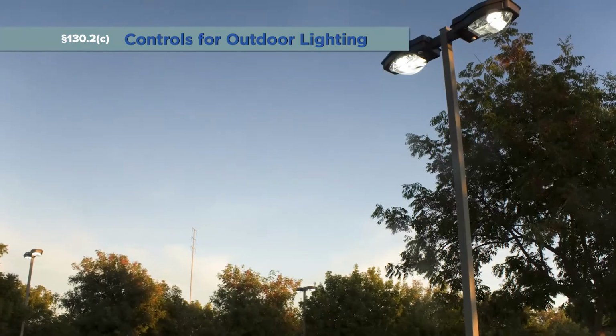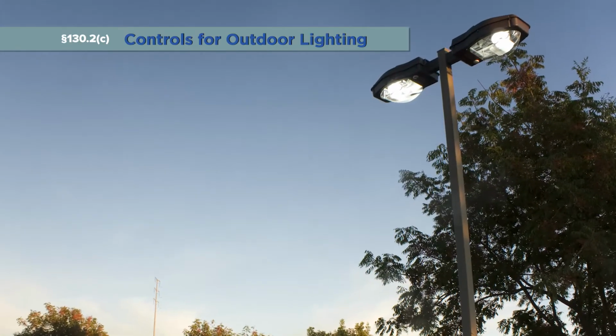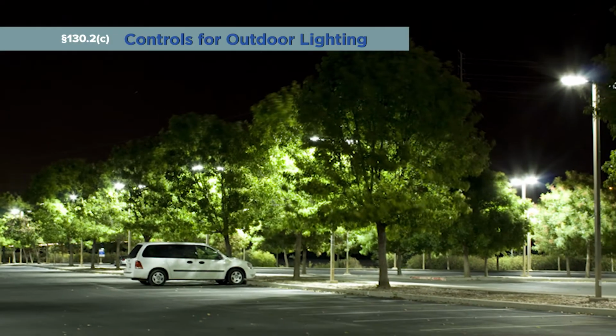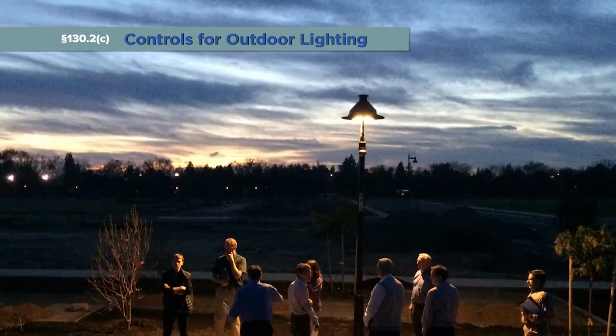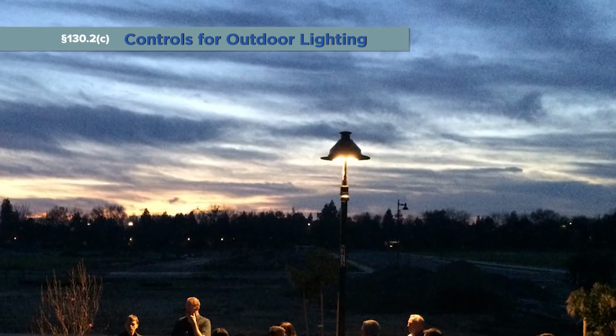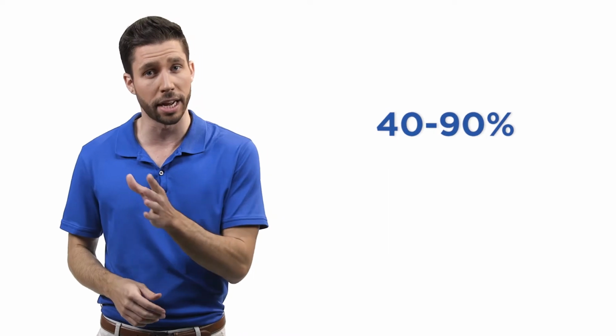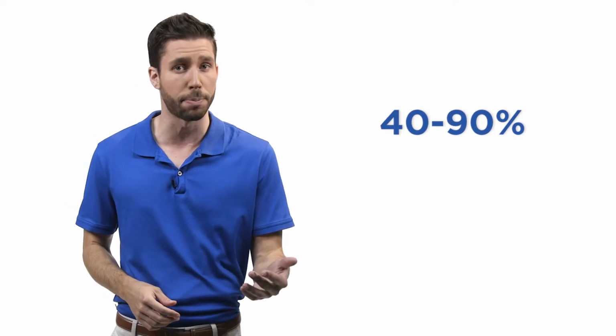Motion sensors in outdoor areas work well as a partial off device, meaning they turn off only a portion of the lights at night. This saves energy and maintains a low light level for safety and wayfinding. These controls must be capable of automatically reducing the lighting power of each luminaire by at least 40%, but not exceeding 90%, or provide continuous dimming through a range that includes 40% through 90%.